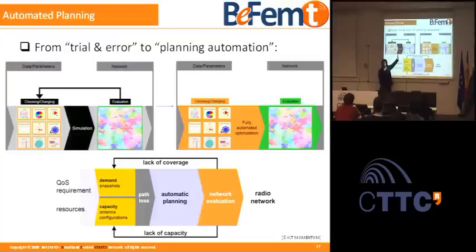The simulation itself may often last for a week. It's a whole network. With CDMA, one base station influences another: a base station in London influences essentially the power control in Edinburgh. So you have to simulate literally large areas, and this takes a long time.